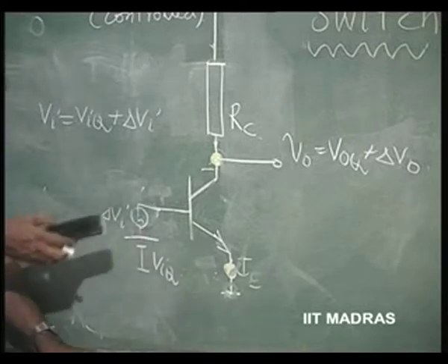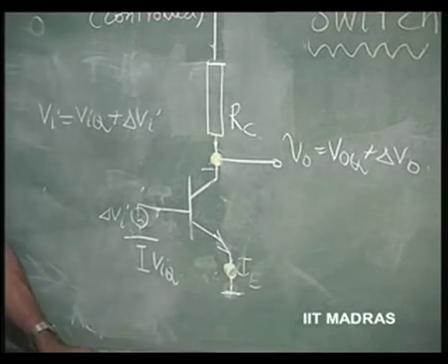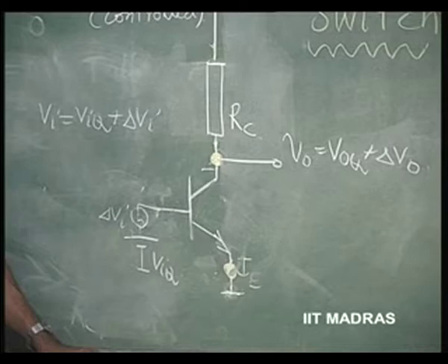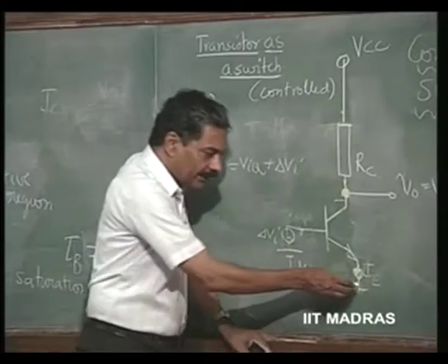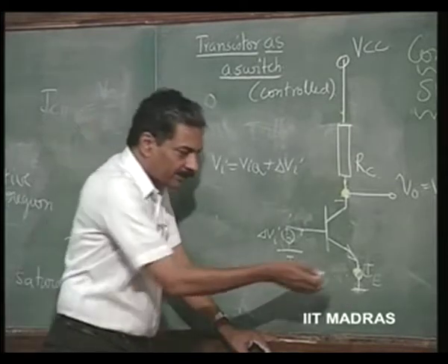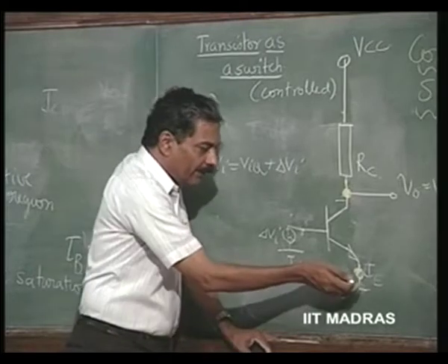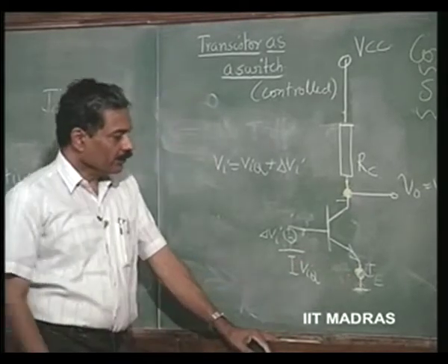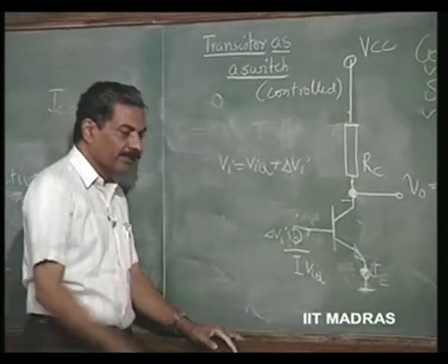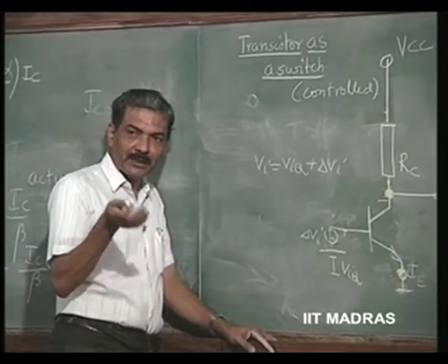In our amplifier design and sources, we have always been talking of a reference common point, and all the voltages have to be discussed with respect to this point. So, the AC voltage should really be applied with reference to this point. Normally the sources are independently coming, and they always give you source voltage with respect to a common ground.